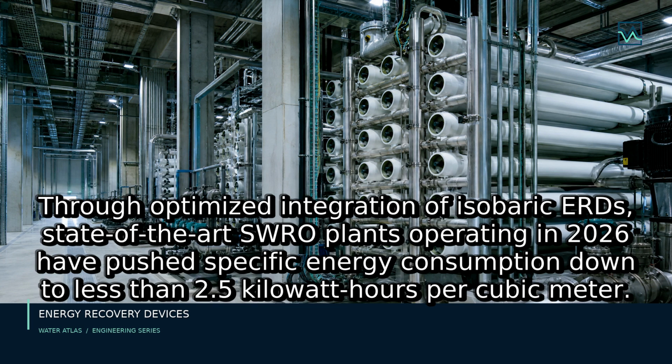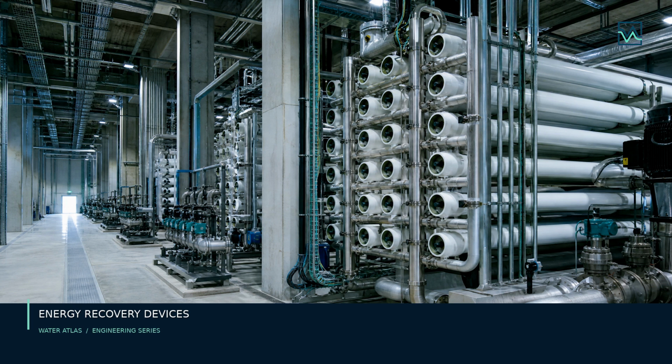In a typical two-stage high recovery setup, the reject brine from the first SWRO pass, which still possesses considerable hydraulic energy, is routed through an intermediate booster pump or specialized high-rejection brackish water membranes. Alternatively, intermediate chemical conditioning or partial hardness removal is applied between stages to mitigate mineral scaling of calcium and sulfate ions. While high recovery configurations dramatically increase water production efficiency and reduce unit footprint, they introduce severe operational challenges.